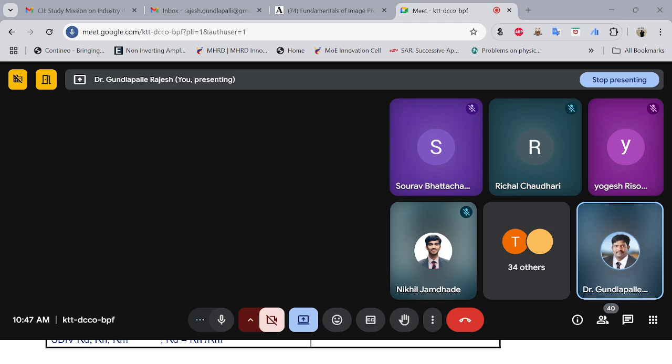Suppose you have an immediate data. The immediate data will get added to your RD register contents, and the result is stored once again back into your RD. So this is what the addition operation will have. The addition operation is straightforward, and we can use three operands.